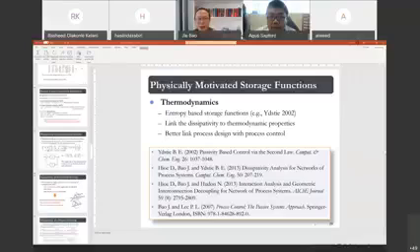Because in that case, if some states are not observable locally, but it's observable when you have the information from the other subsystems, then the dissipativity could be an issue. So in that paper we imposed a dissipativity condition. But if the local system is fully observable, I think we don't need the observer to be dissipative, because the dissipative conditions are actually defined based on the input-output, particularly for MPC itself.